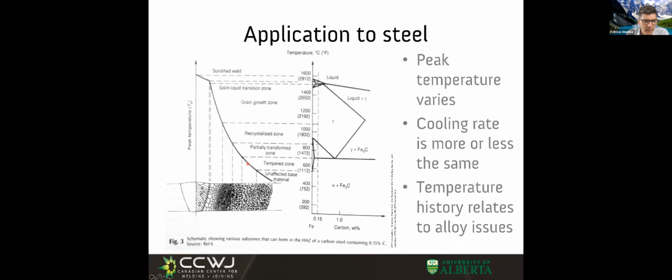If we move a little bit closer, now the maximum temperature that this piece of material sees approaches the transformation temperature. So maybe I'm having some effects here. This effect would be tempering. If I approach the weld closer and closer, my peak temperature is higher and higher.